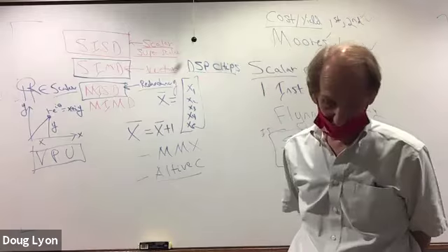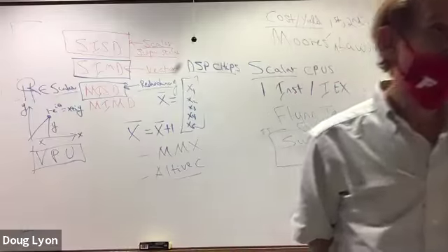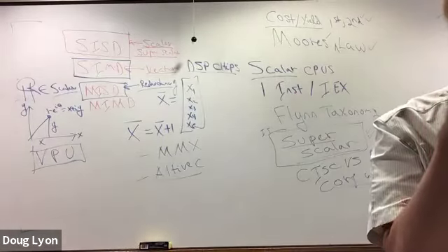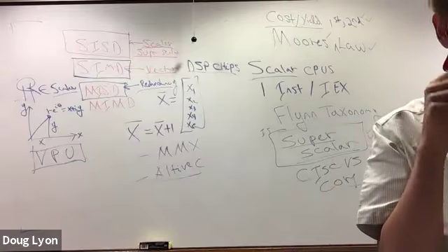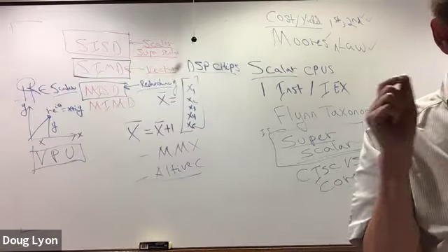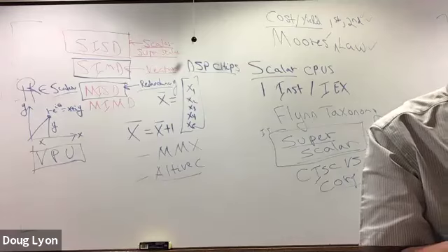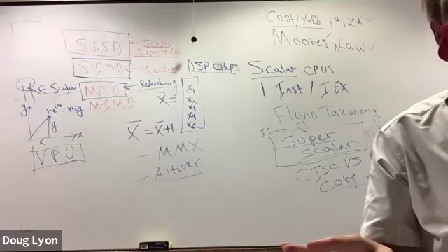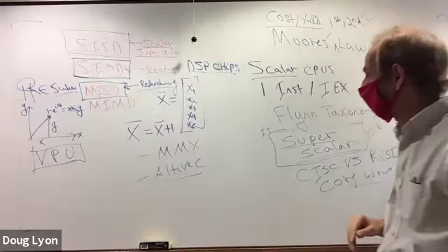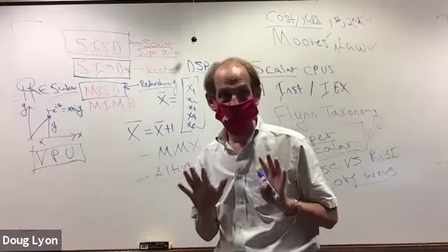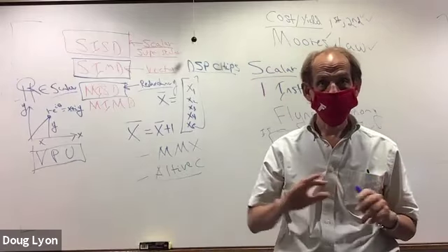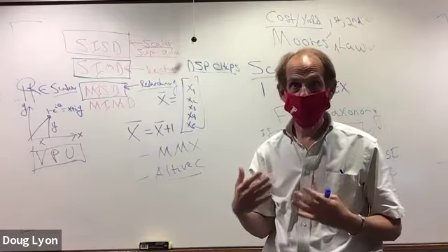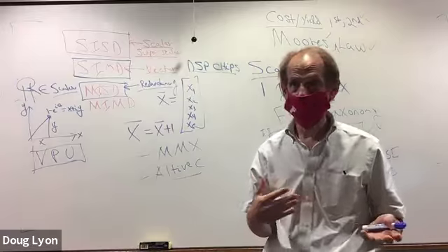In the space station, they have CCD cameras with bad pixels. Little holes in the image. You can barely see them, but if you zoom in, you can see the bad pixels. This comes about because the cosmic rays hit the CCDs and they destroy individual transistors. Cosmic rays go through everything. This is one of the basic fundamental limitations to travel to Mars. Astronauts cannot have enough shielding to prevent cosmic rays from penetrating their bodies.